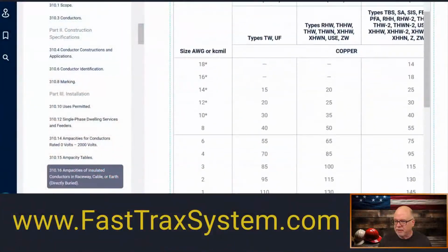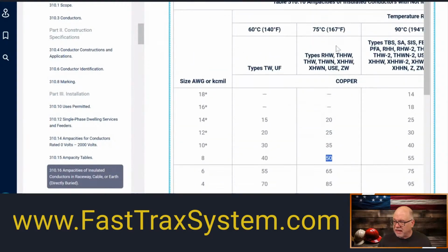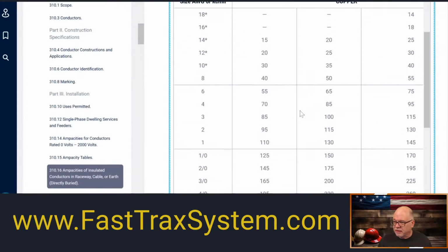And let's see here. We'll go back to ampacity real quick. Anybody got any additional questions? I'm more than happy to answer. So at the end of the day, you're not exceeding that of the 75. And again, your conductor after adjustment or correction is only good for 47.85 amps. Okay. So you cannot exceed 47.85 amps. I don't know what your load is, we're assuming that's what your load is.